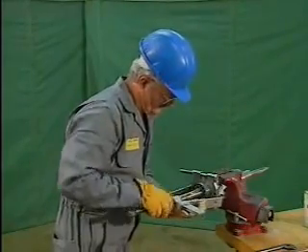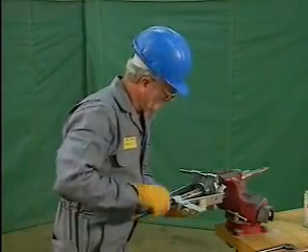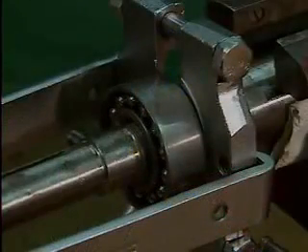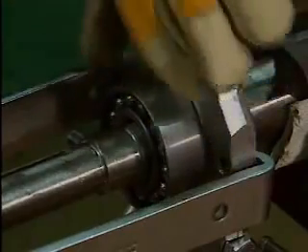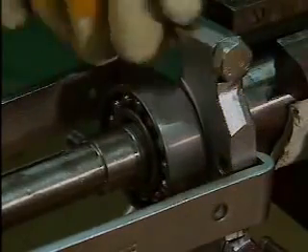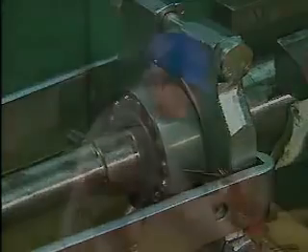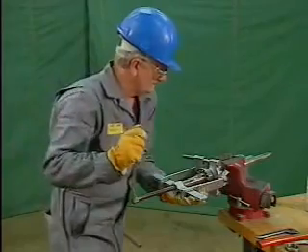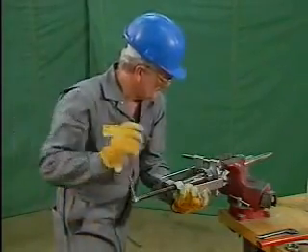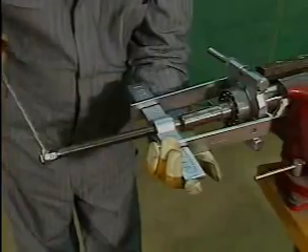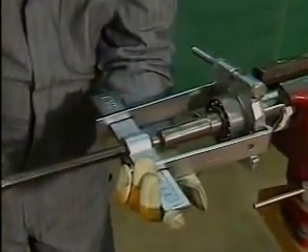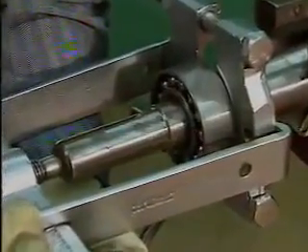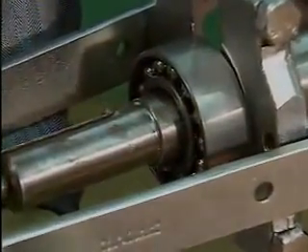He checks the position of the jaws to make sure that they will only push against the inner ring. A good way to check the jaw position is to tighten the puller and then turn the bearing's outer ring. If the outer race can move freely, then the jaws are positioned correctly. Next, the mechanic uses a wrench to tighten the lead screw and draw the bearing off the shaft. He is careful not to cock the bearing. If the bearing is cocked as it comes off the shaft, it will jam and the puller will have to be readjusted. The mechanic continues pulling until the bearing is loose enough to be removed by hand.